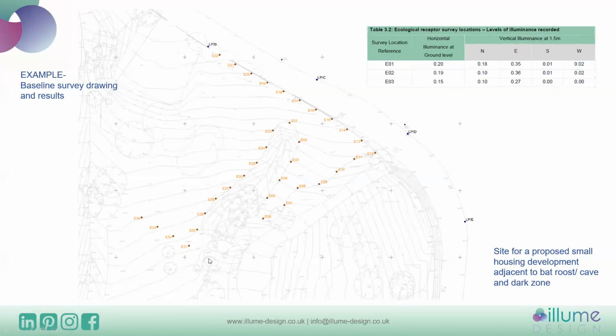Measurements were taken at ground level, measurements of illuminance, and also in the 4 compass directions, so vertical illuminance at 1.5 meters in height, so that we can understand levels of light where the bats were flying in the existing scenario.